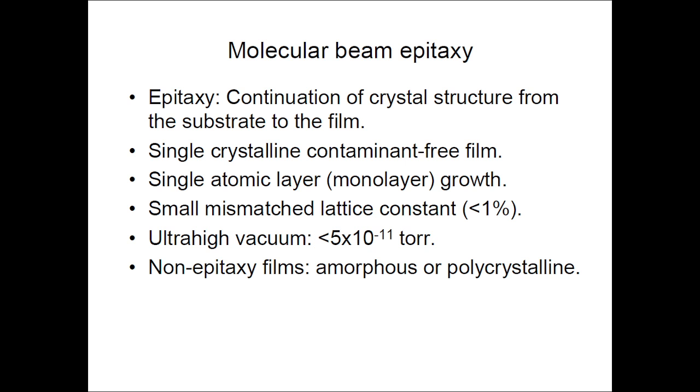Okay, and now the last technique we need to talk about, that is importantly molecular beam epitaxy. As the name suggests, epitaxy, we have a continuation of a crystal structure from the substrate to the film, and a single crystalline contaminant-free film will be there, and we'll have a single atomic monolayer growth, which we will be ensuring in this process.